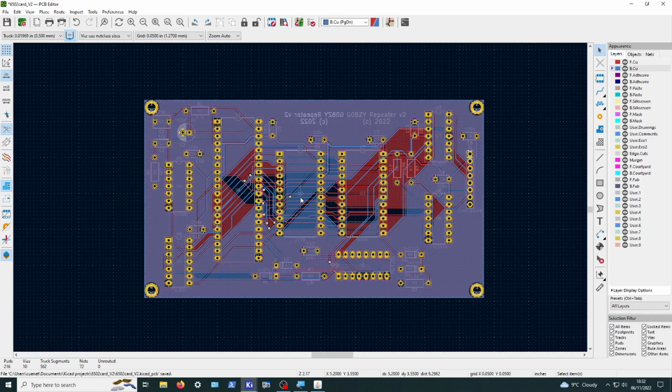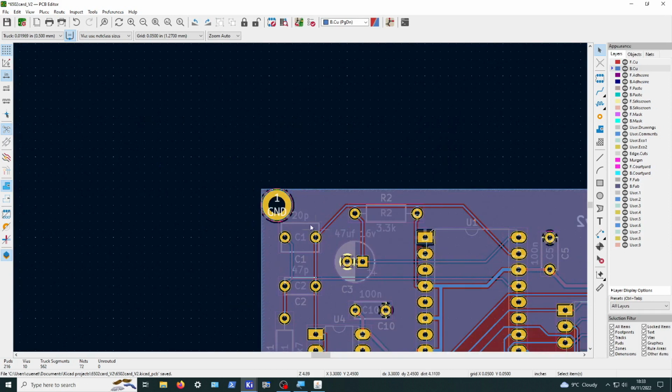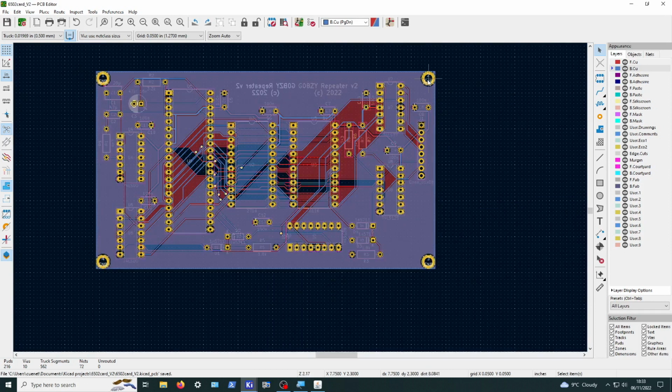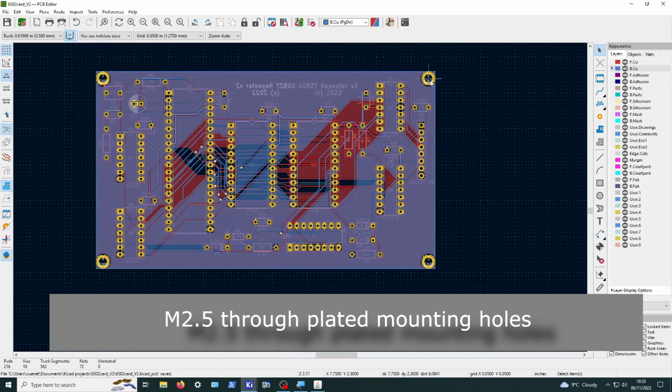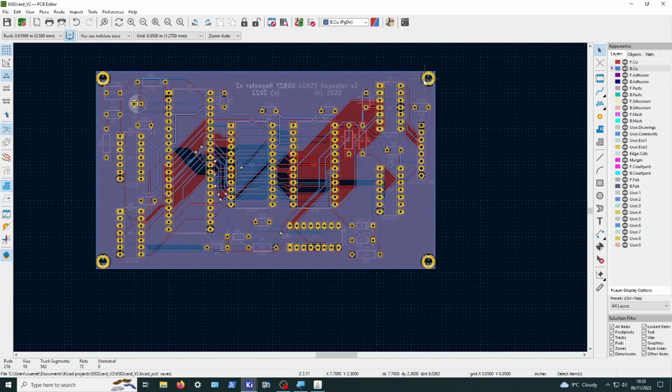Okay, so we've gone ahead and finished the board. At least I think it's finished. I've spent about another hour on it, roughly, just going through the finer points, moving things around a little bit, like the labels and the text and what have you. But the main improvements to finish the board off is we've added the mounting holes. They're M2.5mm with a pad around, so it actually gives you a ground point as well.